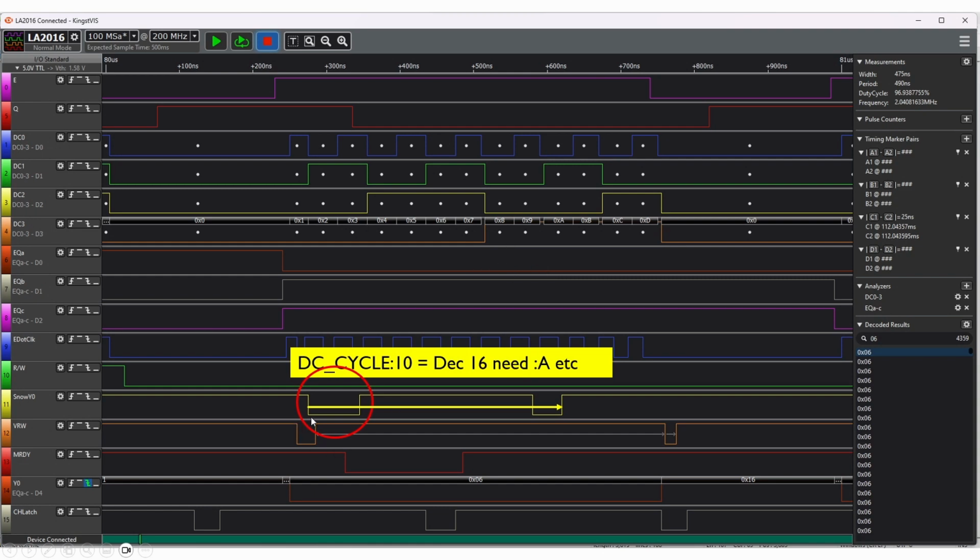What I was expecting was something starting around clock 9 going up to clock 12, which is C here, and in fact the bits that I would expect at the end here were appearing here, because a 1 in front of it effectively went back to 0 and counted again. So that was the reason why these 3 cycles here that would normally be expected to be 10, 11 and 12 were appearing in the wrong place. By switching the configuration to use hexadecimal, that fixed that issue.